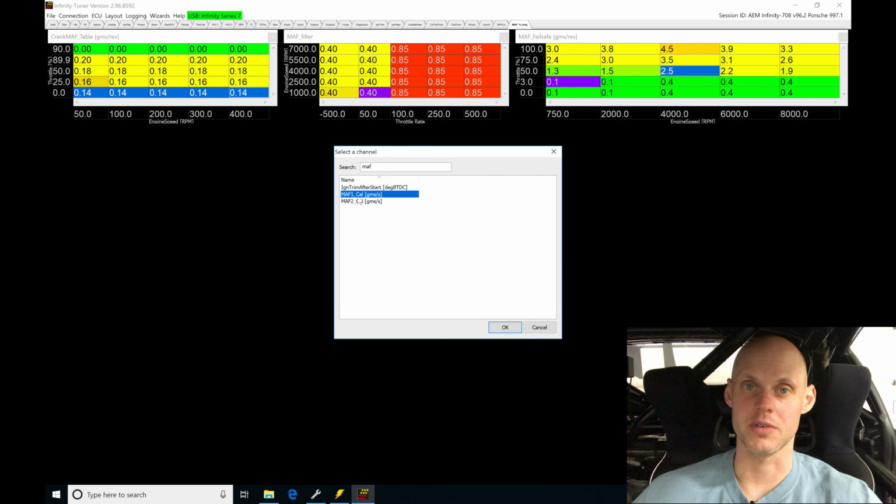It's super simple, as you're going to be finding out, but this is going to be a lookup. So it's going to have a particular voltage value for this mass airflow sensor type. It's a 0 to 5 volt. At a particular voltage, it's going to be looking up what the air mass is going to be coming in the engine. So that's going to be the beauty of the mass airflow sensor. We have to do our job and recalibrate it, but once we recalibrate it, it's going to be very, very accurate. And as our air density changes, if our air temp changes or our barometric pressure changes going up or down in elevation, our mass airflow sensor will directly compensate for that because it's registering or measuring our actual air mass. We're not calculating it based on a map sensor and then a baro sensor.